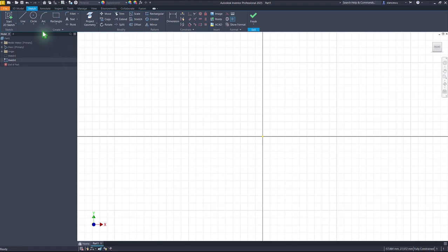You can create entities directly, not only lines. For instance, you want to start with a center line. Activate the tool, activate the center line, go up, then disable this to draw normal lines. Same for construction. Start line, apply construction and draw construction lines.